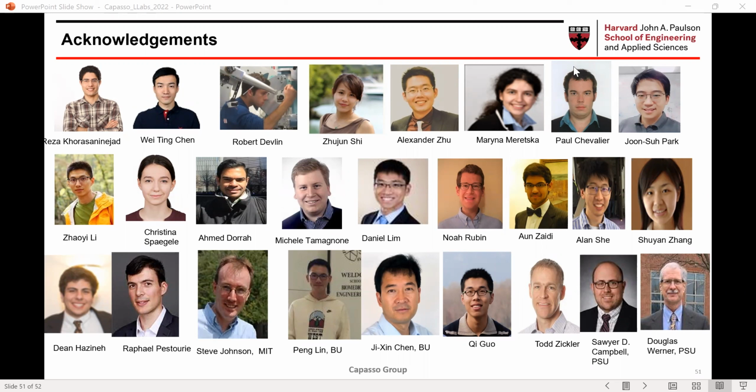We are starting to explore applications because in my group we have developed in the last year a widely tunable terahertz laser, tunable from 200 gigahertz to more than a terahertz. So we are exploring the use of metaoptics to manipulate these terahertz beams. This incidentally is a room temperature laser.